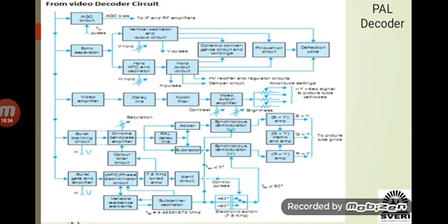Now PAL, if you compare with NTSC, obviously NTSC altogether is a different system, because NTSC works with 525 lines. Its operating frequency is different for vertical scanning. Then it will be using altogether a different methodology. But in NTSC, in early days, the phase shift error has occurred. NTSC is mostly preferred in the American subcontinent, and in America there was a hardware tool which has been derived to ensure that if at all phase shift error occurs, that error will be eliminated.